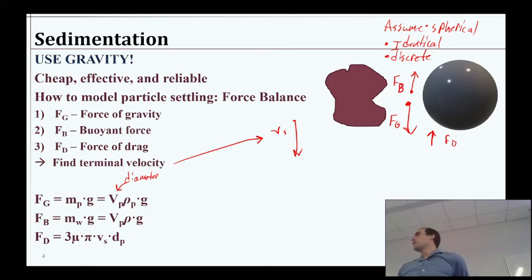The added advantage here is if we already go through the trouble to figure out the volume of these particles, then we now know the volume of the water displaced, and combine that with the density of water, we can get a term for mass with values that we can actually use in our system.